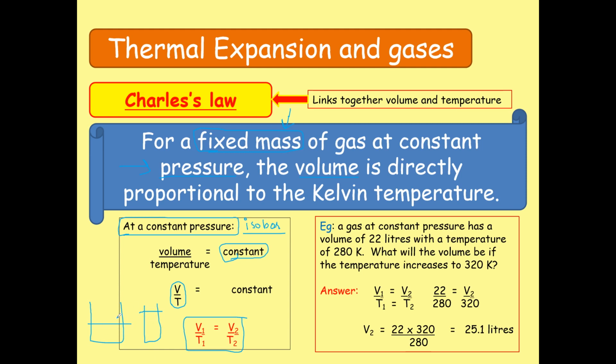Don't mind if you see a difference in the drawing, I'm just doodling around. The temperature change will induce a change in volume. Why? Because the pressure we're applying on it, the weight on it, is the same. The mass is the same. This could be a mass, or it could be just the atmospheric pressure. But at atmospheric pressure we cannot hold a gas in a container, it would just move out and escape. So we need to keep a lid with a fixed mass on it, so that the gas does not escape our container.